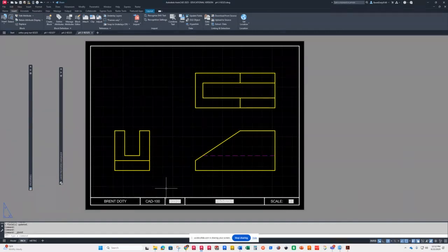It is. Now, here's something else to look for. Does your line type show up okay? Well, these hidden lines look good to me. The object lines are obviously fine. So, yeah, we're good. Now, later on, there's a thing called line type scale, or LTS, that we can adjust to fix if our lines don't show up the way we want them to, which when we get to the metric one, we'll have some issues.